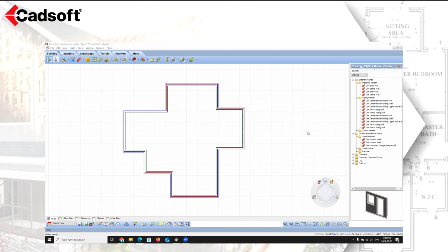When you use the Roof by Picking Points tool, you can freely pick points to define the outline of the roof anywhere you want in your design. Each method is suited to a different purpose and has its own advantages. The method you choose will depend on where your roof structure will lie in relation to the model's walls.